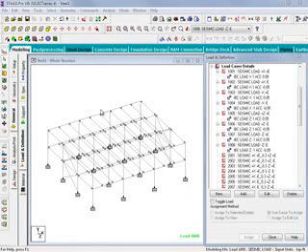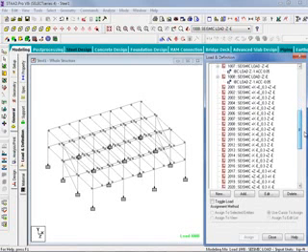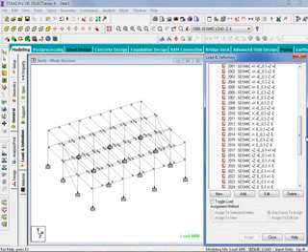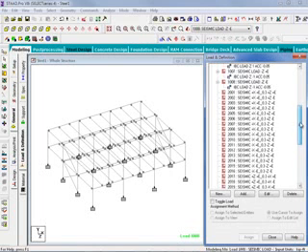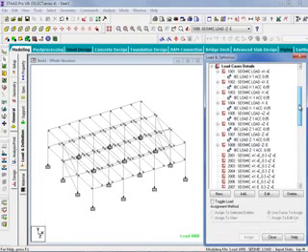In our sample model, we've already created several seismic load cases in the 2000 series load cases area to represent these orthogonal effects that we're going to be applying to the model. Again, I can use my basic primary seismic load cases as my building blocks to create these orthogonal effects. Let's go ahead and see how we would do our first one.